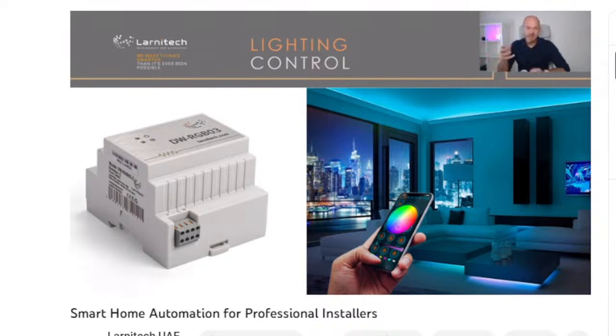LED can be one color, can be different color temperature, like warmer, colder, cooler, and can be color, RGB, can be RGB with white, RGBW, and can be RGBWW, so RGB with tunable white. So all of these you can control from this device. This device is specially for 12 volts up to 24 volts light fittings and lights, but we have different types for 230 volts and so on.